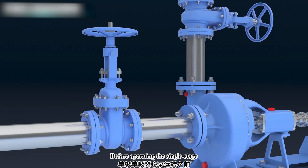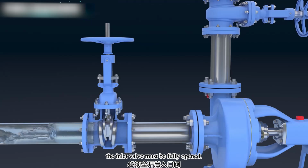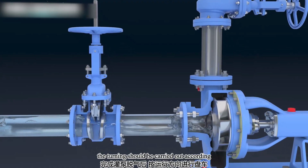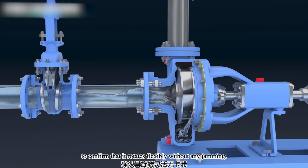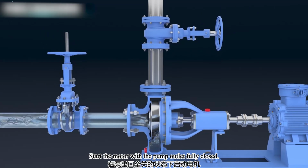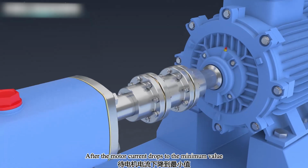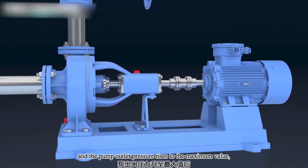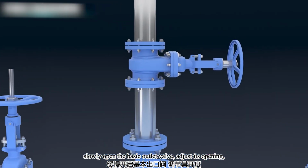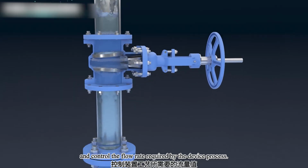Before operating the single-stage, single-suction centrifugal pump, the inlet valve must be fully opened. After completing the pump degassing, the turning should be carried out according to the operating direction to confirm that it rotates flexibly without any jamming. Start the motor with the pump outlet fully closed. After the motor current drops to the minimum value, and the pump outlet pressure rises to the maximum value, slowly open the outlet valve, adjust its opening, and control the flow rate required by the device process.